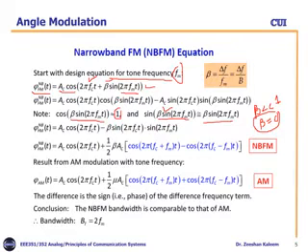So phi narrowband FM, we can write after using this in equation 1. For example, we name it as equation 1. So putting 1 here and beta sin 2 pi f_m t only here, we will get A_C cos 2 pi f_C t minus beta sin 2 pi f_C t into sin 2 pi f_m t.